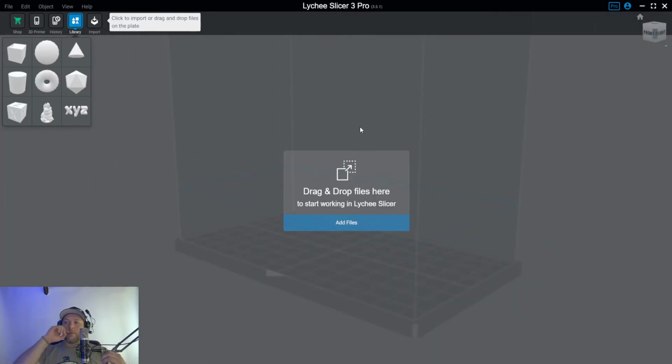So real quick, while we got a couple minutes left, let me switch over to a different camera I've got set up for you guys. We're going to have a quick look at a couple of failures in a print or two prints that just got missed when we were placing supports in them. Keep in mind the resin I use for test prints is lesser quality, so it's kind of powdery. It rubs a little bit. I try to use up old resin when I do test prints.